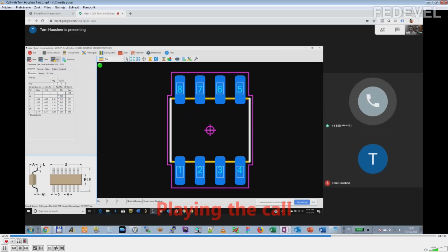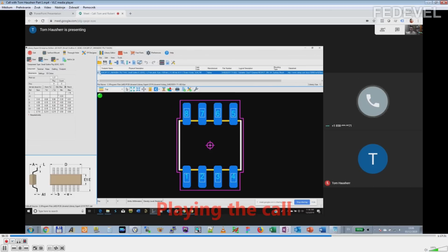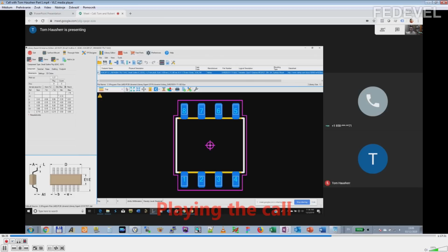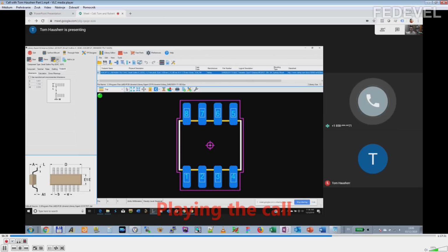Select the OK button here. Oh, let me see here. I'm going to reopen the part. But now I got the linear pattern there. Now I'm going to uncheck it and select OK. And then, wait, component. Oh, it's back here. Let me change this to 0.03 again. When I reopen the part, see, now we trim the pads from going underneath the part.